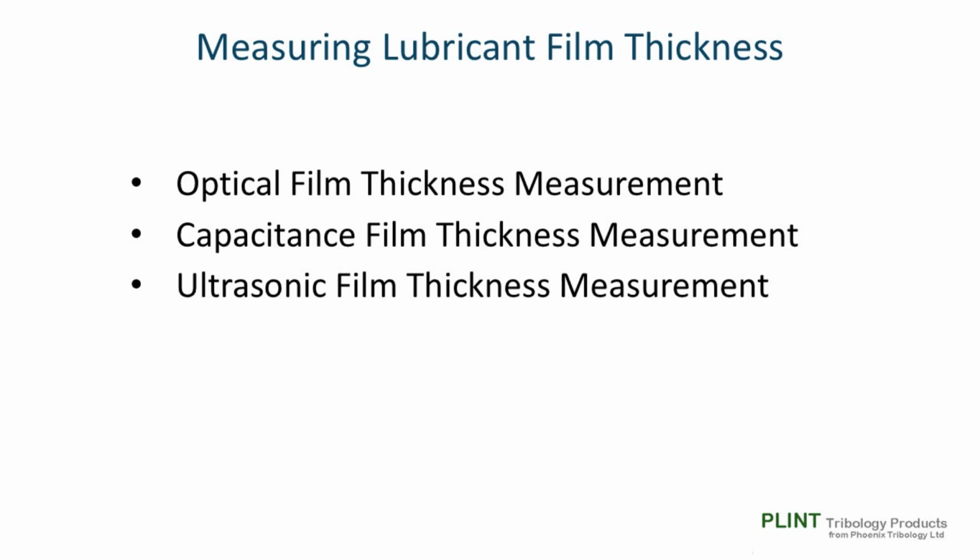However, the method suffers from one serious limitation: the strength of the coated glass. Because of this, contact pressures cannot exceed about 0.8 gigapascals, and in order to preserve the coating are typically limited to about 0.5 gigapascals.